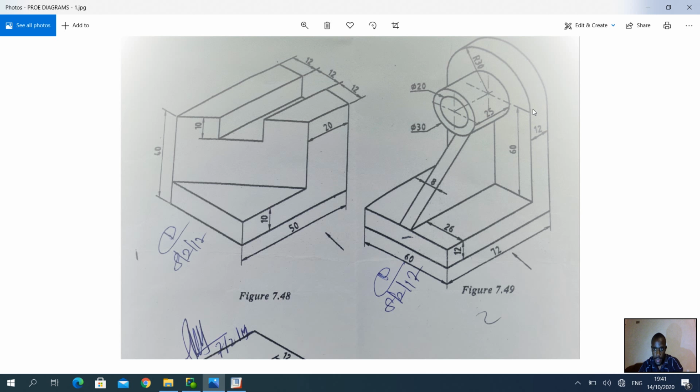Then after that, I can make the semicircle, and I can extrude it to the 12 distance, and then I can make these two concentric circles, the hollow cylinder, which is protruding from this surface here, and then I'll end up by making the rib. So the L shape, the circle, the cylindrical component, and lastly the rib. That's the sequence of steps that I'm going to be executing in making component number 2. So we start to have a lot of components here, but the formulation is still the same.